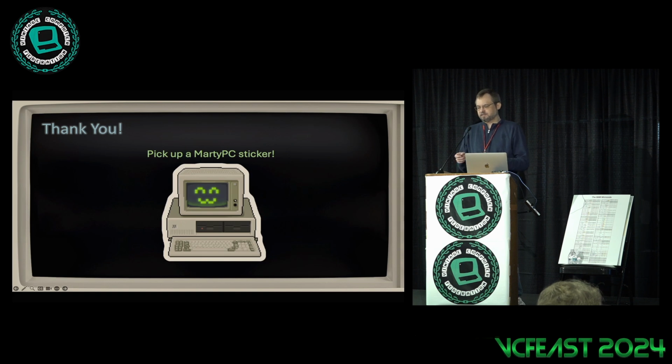So what I'm doing is working on a new version for the Giga. Being that it's much faster, it should be able to clock the CPU at native clock speed, which would reduce that. So what we would have to basically do is give it the program to run, let it do its thing, and then dump it all from memory, because you can't just control it back and forth. Even over USB 3, the latency is too high.